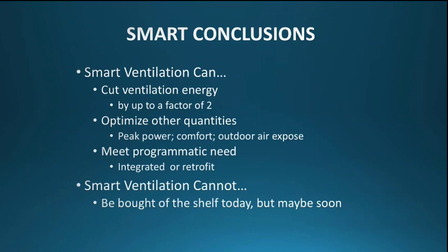So let me wind up with some conclusions here. What smart ventilation can do is it can cut the ventilation energy quite substantially compared to a simple mechanical ventilation system. It also gives you the option of optimizing other quantities of concern as we build buildings in an integrated manner, where we look at demand and peak power, we look at comfort issues, we look at exposure to outdoor contaminants, we look at utility pricing systems. You can optimize all these other things and still know that you're providing acceptable indoor air quality.